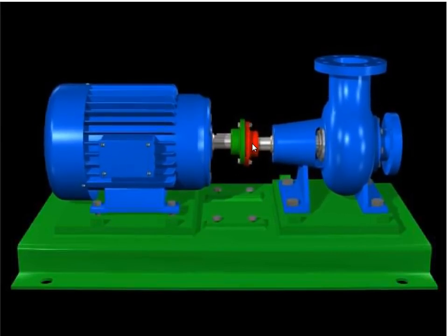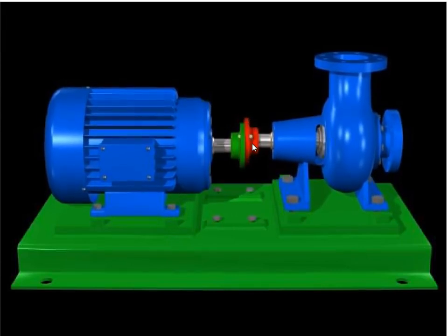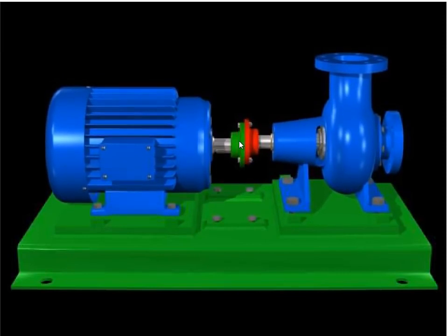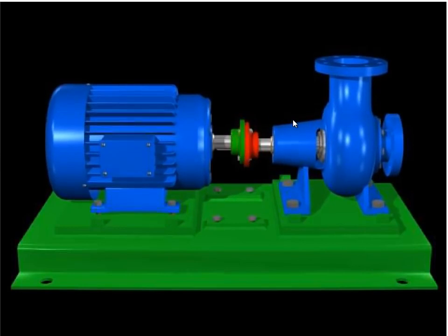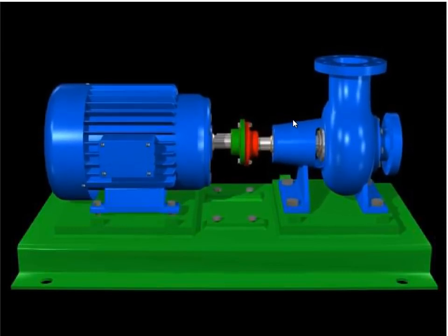We've got the bolts undone and it's free to move up and down. Maybe we're out in space. But of course we're going to bolt the machine down, but the forces are still there. So if I put a sensor here and a sensor there, they are 180 degrees out of phase, whether I measure them both vertically or measure them both horizontally.